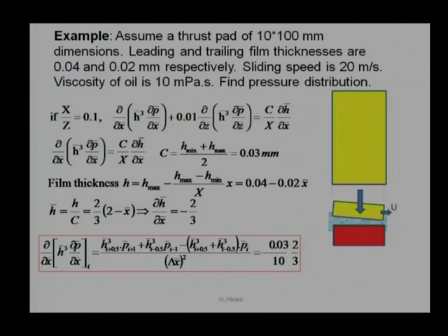First, we will consider the finite difference method. So, we know this term, and we know how to represent this derivative of the pressure term in terms of a finite difference equation, which was learned in the last lecture. That will turn out to be h bar cube at i plus half times p i plus 1.